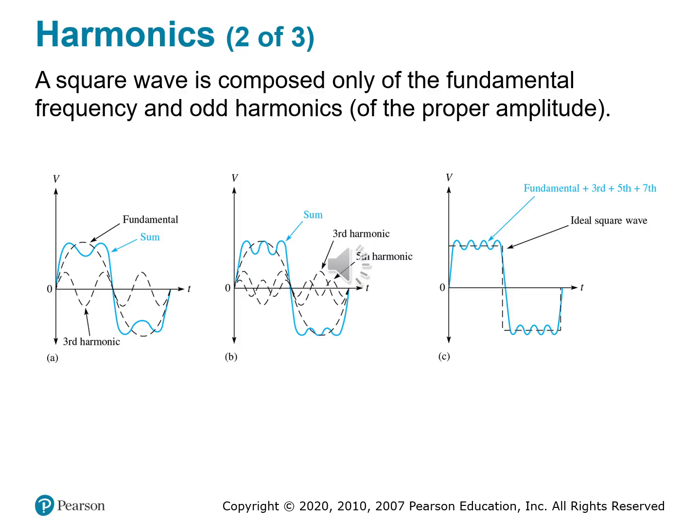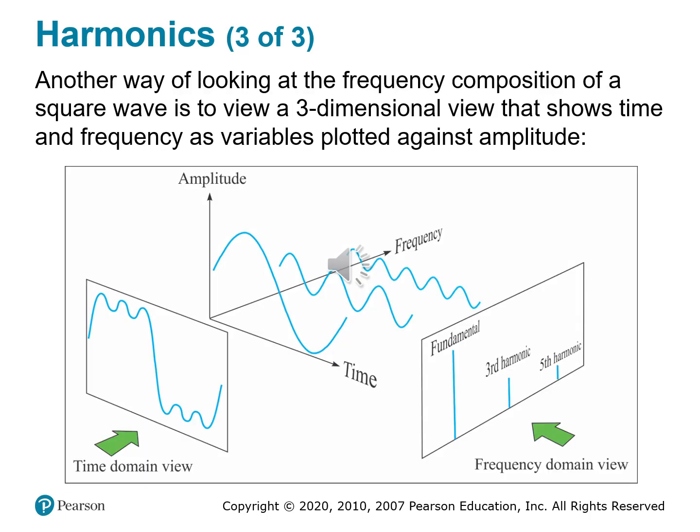They have a frequency that is an odd multiple of the fundamental: 3 times the frequency, 5 times the frequency, 7 times the frequency. It has specific amplitude and phase, adds detail and edge definition to the final shape, and this whole process is called Fourier synthesis, reconstructing complex signals from simpler sine waves.